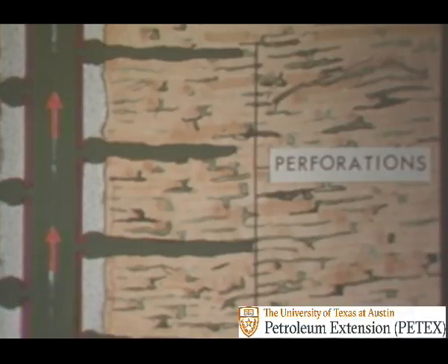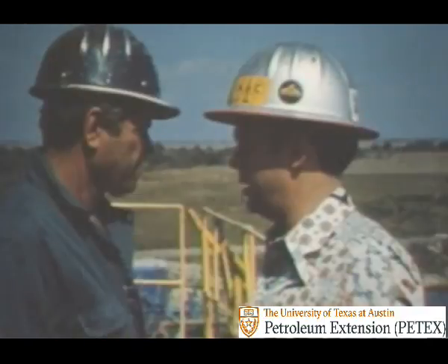The liner is perforated opposite the pay section and finally tested to determine if it's a producer. The company man tells the pusher that the well tests out okay, and from all indications shows no blockage of the pay. So it looks like the oil mud has served its purpose well.